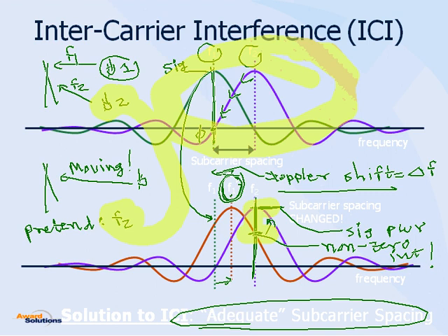LTE is okay. LTE supports 3 duplexing methods: the regular FDD, frequency division duplexing, and then we have TDD, time division duplexing, and we have half FDD. So we support all 3, and our current view is that FDD will be the default deployment configuration in early LTE deployments. So early deployments of LTE you will see FDD. Later on you will see TDD, but early deployments FDD.